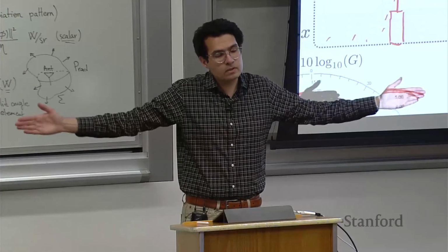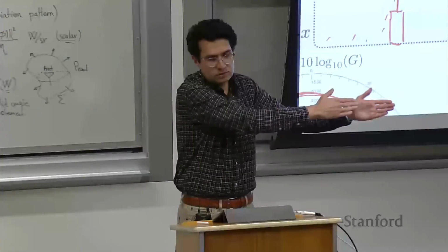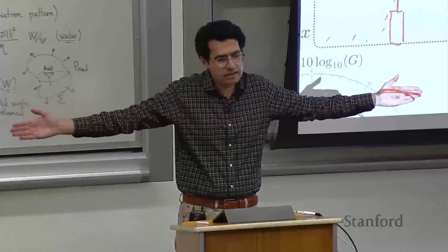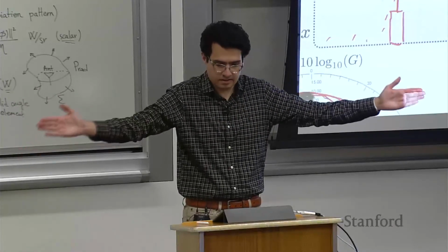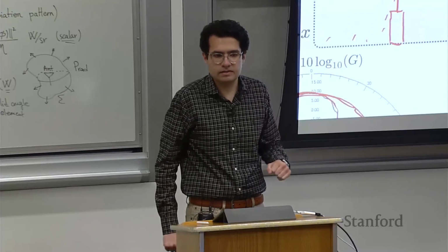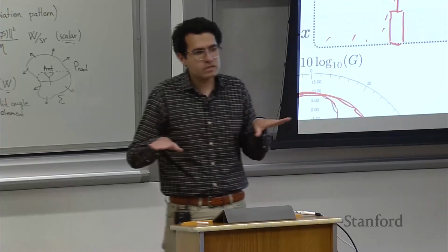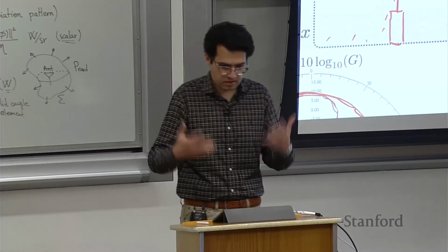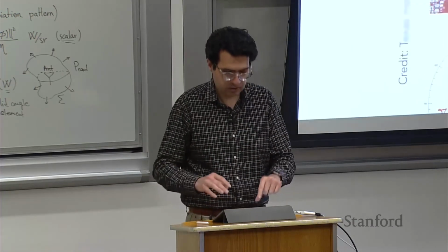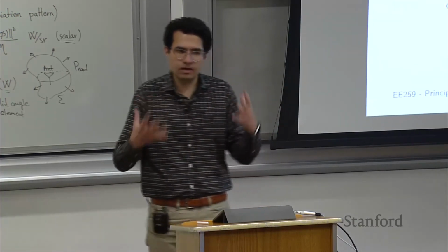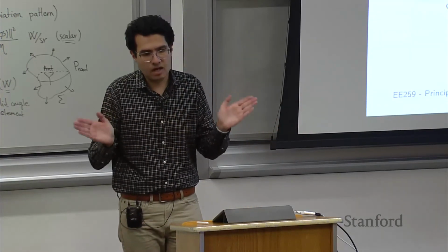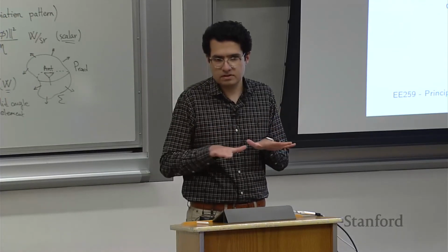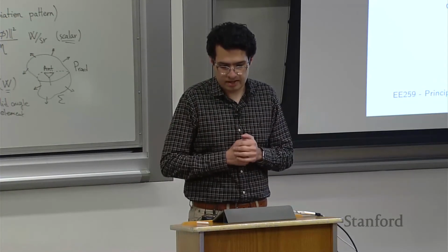But horizontally, you want a very wide beam pattern, right? We want to be able to see things for as wide as possible. Ideally, they would have loved to have a full 180 degrees, but that's not physically possible. So they got close to it, like 120 degrees or so. So that was a design. It didn't just randomly happen to have this radiation pattern. People thought about what the use case of this antenna is, what we are going to need to sense, and then they designed a geometry that gives them a desirable radiation pattern.